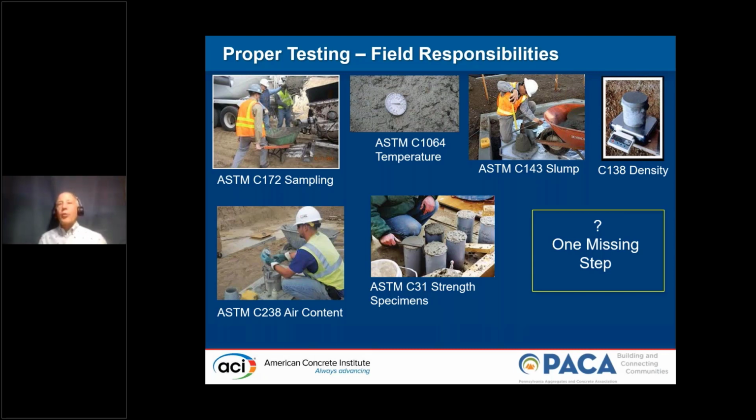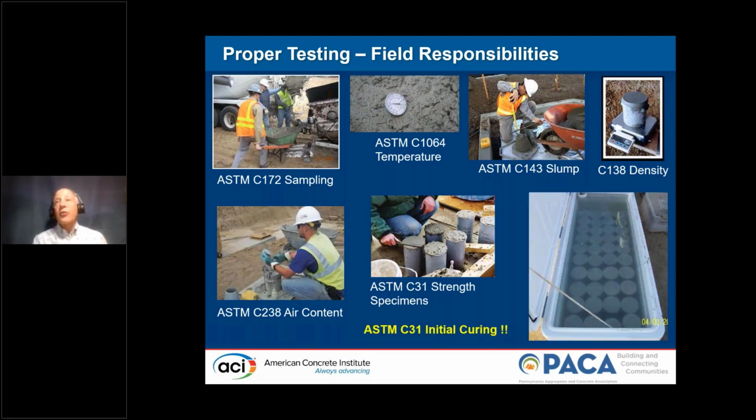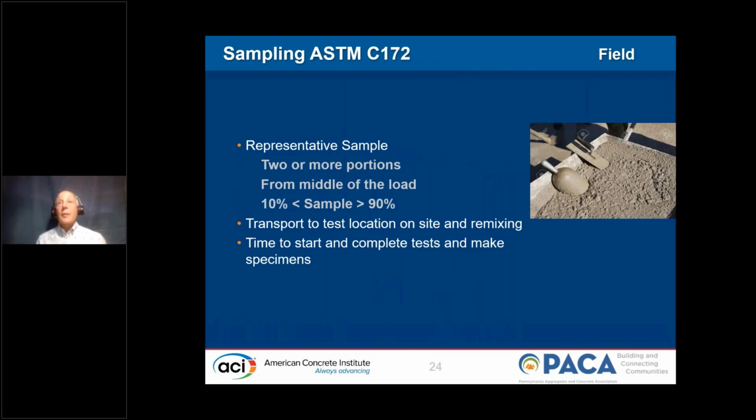Well, there's one missing step, and it's this step where this system breaks down most often. And that is, we need to provide proper initial curing for those strength test specimens. And that's a requirement under the ASTM specification and in the building codes that we rely on. Let's look at each one of these real closely for a moment or two.